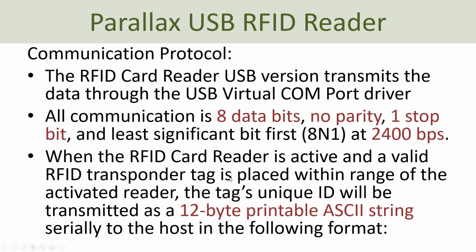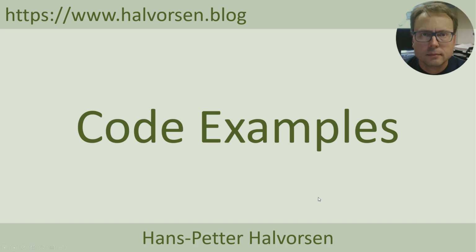And this particular system generates, so each tag has a unique ID, and these tags have a 12-byte ASCII string that you can read in either of these programming languages or in serial monitor software. Next I will go through some code examples. First I will show an example in Python, then in LabVIEW, and finally in Visual Studio and C#.